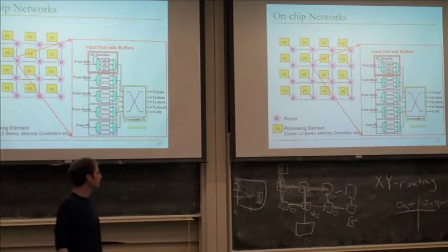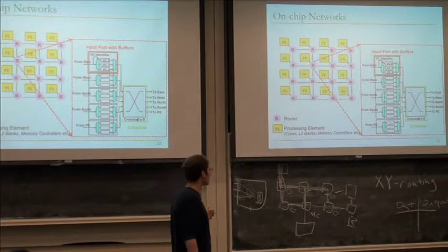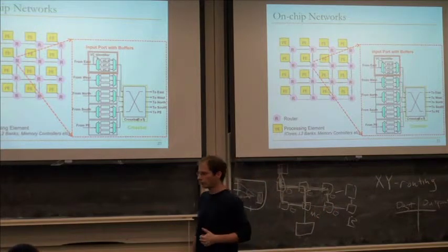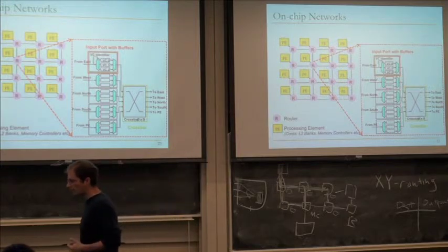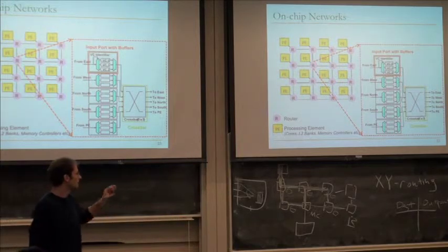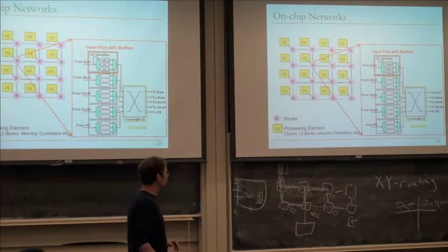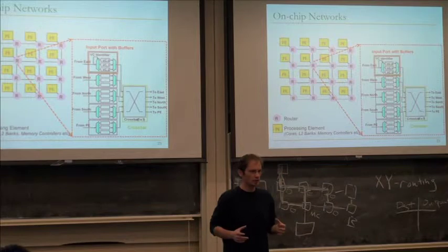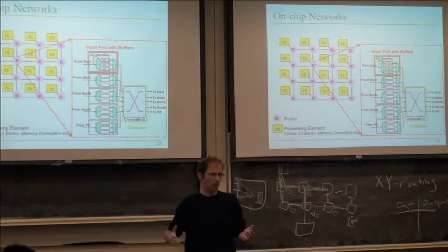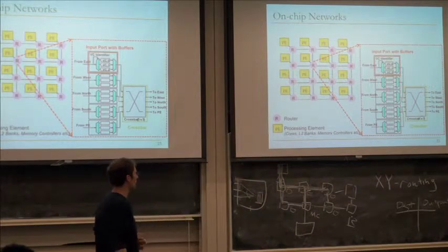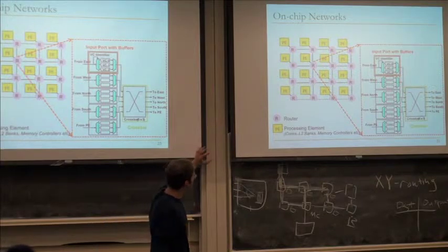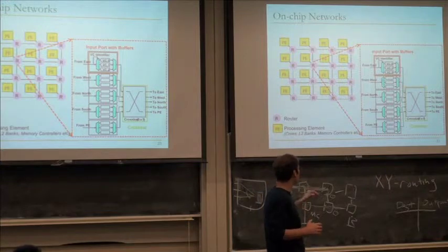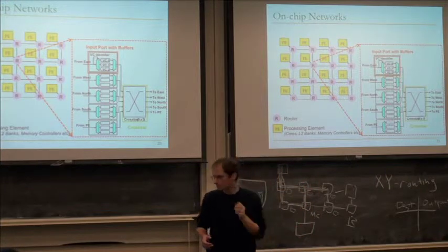Okay, and then once you buffer the traffic, eventually you'll decide that this flit needs to go to this router output on toward its next hop. In order to make that happen, you have something like a crossbar. This could be literally a full n by n crossbar. It could be some more efficient, sparse data path like a log step network or something, an indirect network. But basically you have some data path that connects the input buffers to all of the router outputs. So if traffic arrives from any input, it can get to any output.